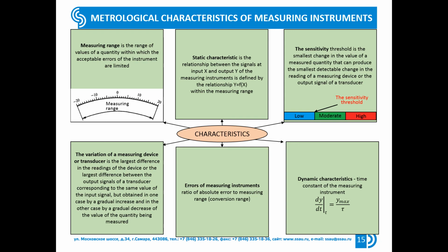The time constant of a measuring instrument is one of its possible dynamic characteristics. If the signal at the input to the device changes instantaneously by some amount, the output signal may only reach saturation after some time. For example, a hot junction of a thermocouple is quickly lowered into boiling water. As the junction and leading wires warm up, the thermocouple thermo-EMF will change, reaching a maximum value after equilibrium has been reached. The relationship of the output signal to time is sometimes expressed as an exponent.